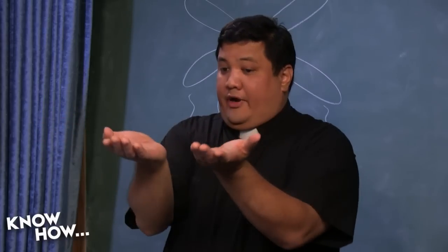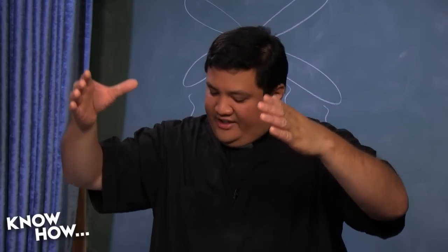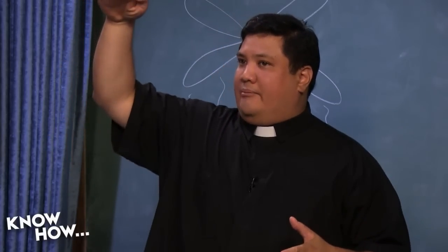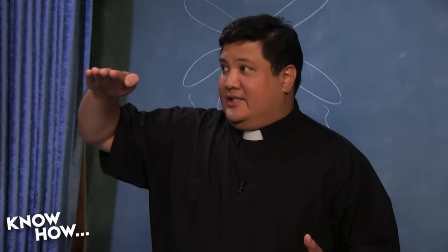There's someone, I think it's Titus, who is also Dirty Air in the chat room. Well, he was talking about how, remember I showed you that frame that would angle the motors outwards, right? Yeah. Well, that's actually a really good way to avoid it altogether, because you're never descending into your own prop wash. The prop wash is always going off to the side. Isn't it the DJI Inspire, or the really nice one that has the arms that go up and they kind of angle out? It just gives you that much nicer descent, because anyone who has flown will tell you descent is hard. Going up's easy. Yeah. But when you descend, it starts to get bumpy.